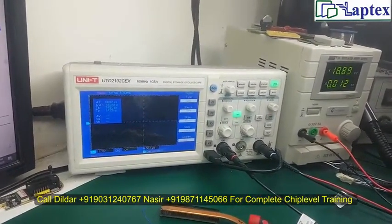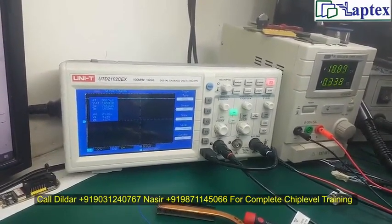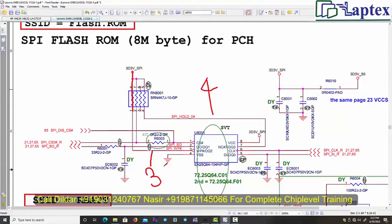So now, as you know, this is the suspend logic, and you will get the voltage after turning on your motherboard. Now you can see no glitch, no ripple. A straight DC line must appear on your DSO, and now you can see 3.22 volt is available on pin number 3, that is the write protection.